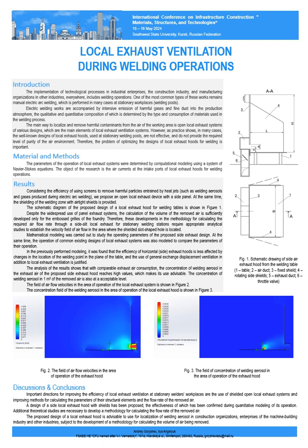In most existing designs of local suction systems, there are no screens, which allow, firstly, to protect the exhaust area from periodic or constant exposure to blowing air flows, which disrupt normal operation and sharply reduce its efficiency. Secondly, using screens of various designs, it becomes possible to significantly reduce the required volumes of exhaust air.